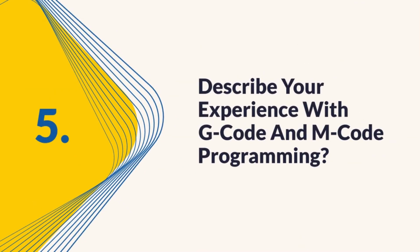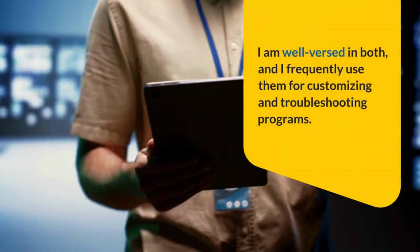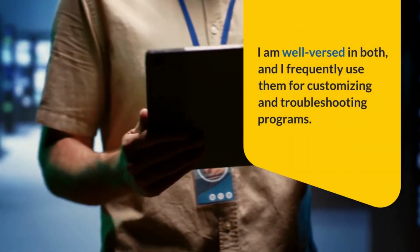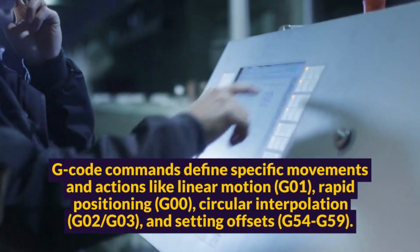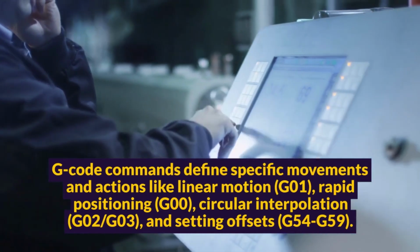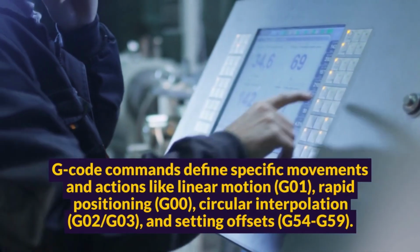5. Describe your experience with G-code and M-code programming. G-code and M-code are the foundational languages of CNC machines. I am well-versed in both, and I frequently use them for customizing and troubleshooting programs. G-code commands define specific movements and actions like linear motion, G01, rapid positioning, G00, circular interpolation, G02, G03, and setting offsets, G54 to G59.